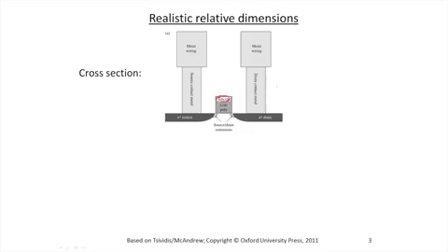All of this region here is filled with silicon dioxide, and through that you cut holes in order to make contact to the source and the drain. So these two areas are the contacts, and you fill them with metal. And the metal makes contact between the source and drain and the wiring which connects your device to other devices on the same chip. For example, this could be the cross-section of a wire that runs perpendicular to the surface of the slide.